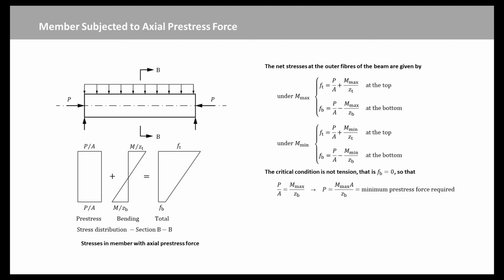Similarly, the stresses immediately after pre-stressing, before losses have occurred, may be calculated if the value of losses is known. For example, the maximum stress in the top of the member is derived as these equations. It can be seen from the stress distributions in this figure that the top fiber is generally in considerable compression, while the bottom fiber is generally at lower stresses.